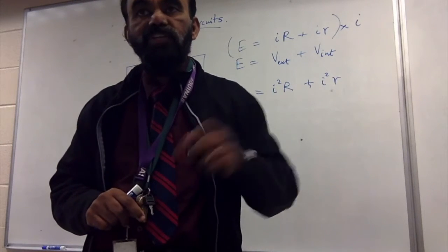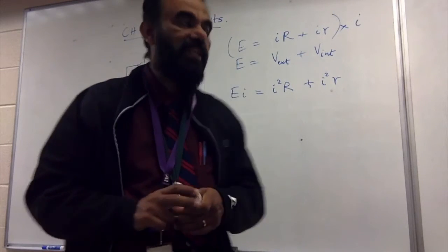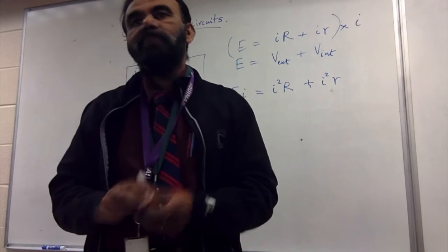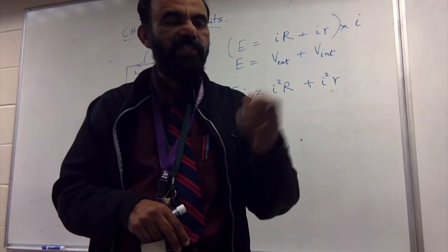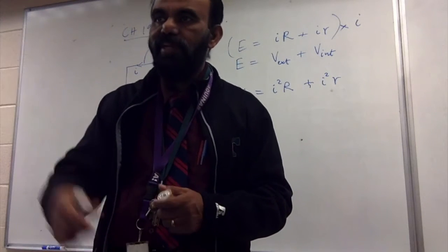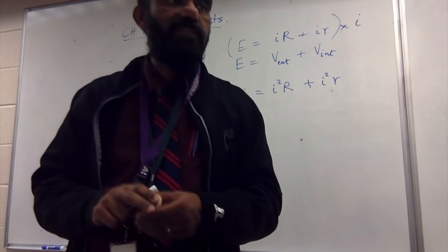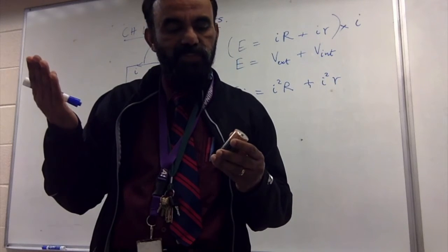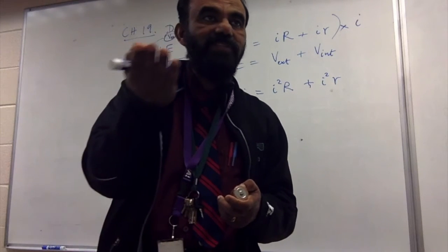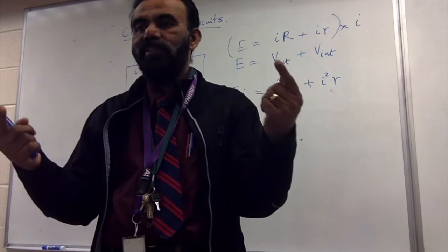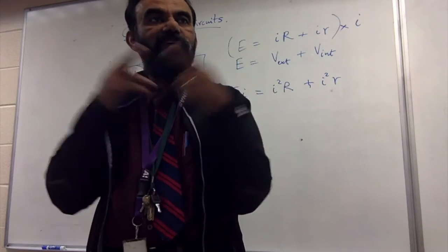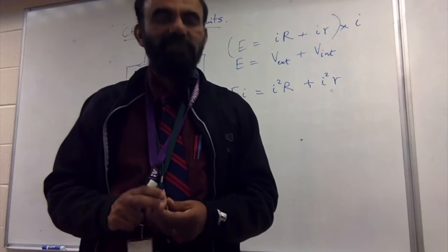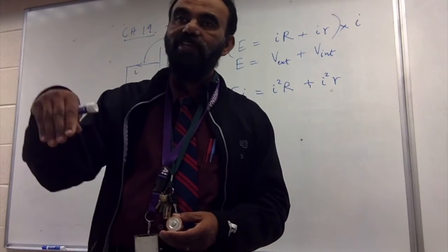Okay. Now a rechargeable cell normally is not 1.5 volts, it's only 1.2. But the internal resistance is much lower than these. That's why they are on the stronger end. You can use rechargeable cells for stronger applications. When you're using a rechargeable cell, its internal resistance will change. But when you recharge it, you're working the chemical reaction the other way around, and you're kind of undoing what was done. And that's why the cell regains its capacity. Internal resistance drops after you charge it, and everything goes well.